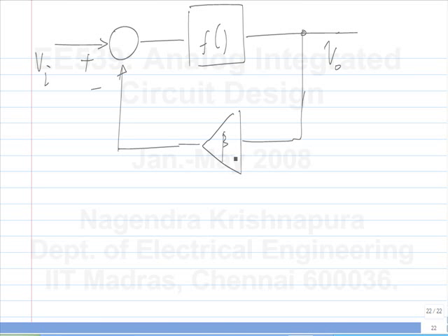So F is some nonlinearity, beta is the feedback fraction, so you get V naught times beta here. Was everyone able to solve this problem? What did you get to be the answer? What's the idea? So F is some nonlinearity, but what's the bottom line? What do you get out of the circuit? G is similar to F. Okay, that's not very interesting, right? The nonlinearity reduces drastically. That's what you should have inferred, but let's analyze it and see.